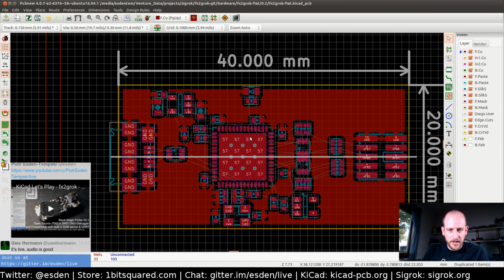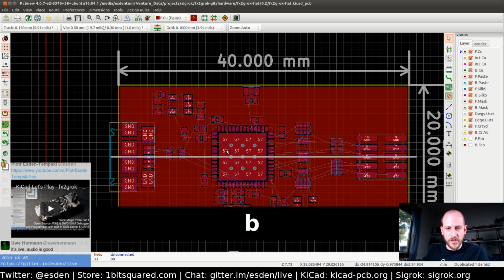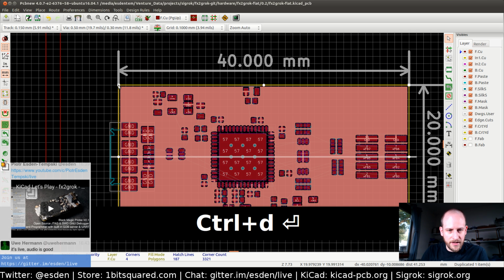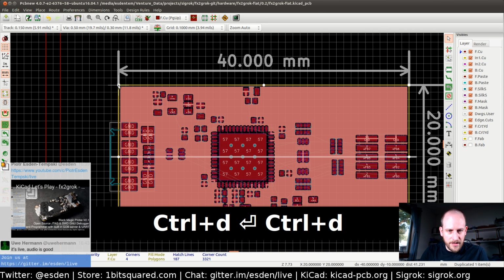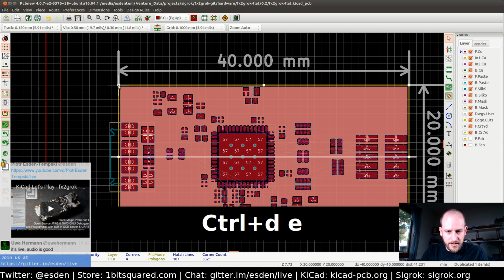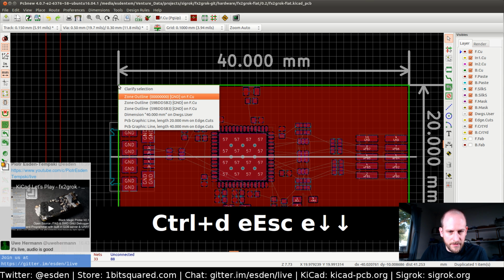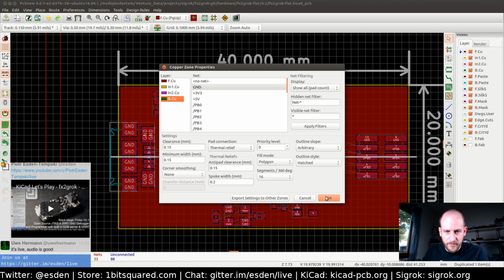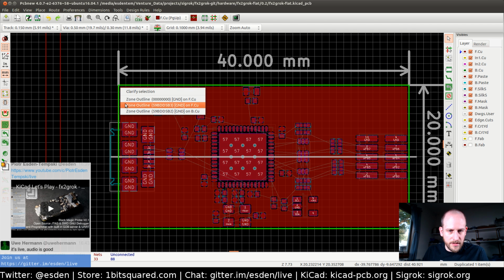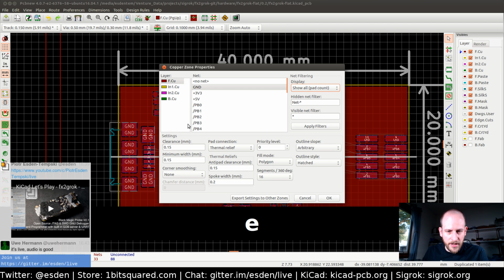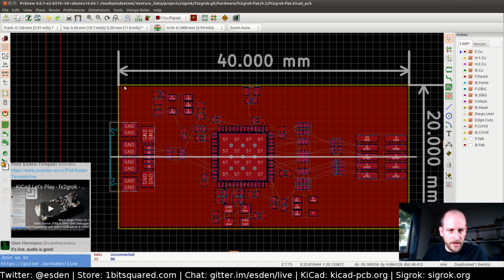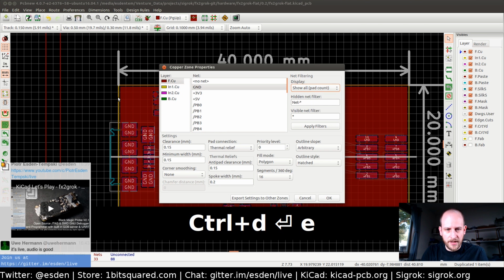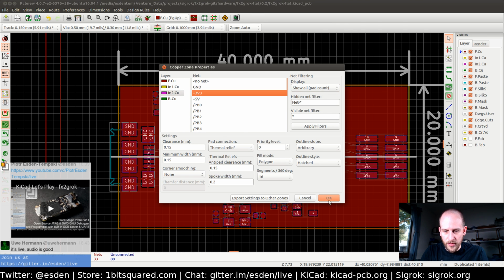So now, if I recreate it, it's much tighter. So it fills the layers tighter. Now we can duplicate it, and duplicate it. Edit, edit, F copper, and set it to backside, and F copper, edit, and put it on the inner copper, and then take the turn, duplicate, enter, edit, and put it in inner on 3.3 volts. Okay.